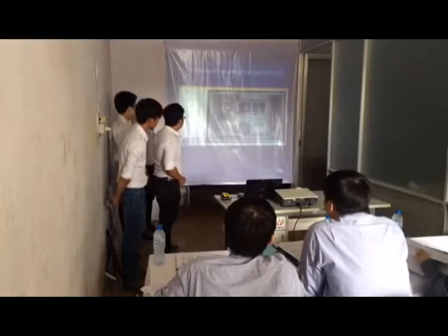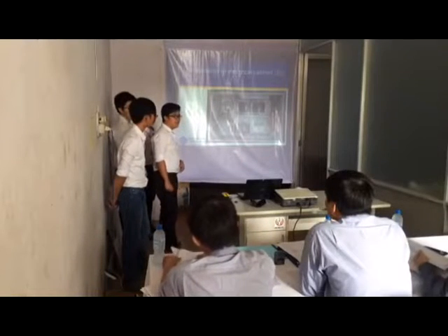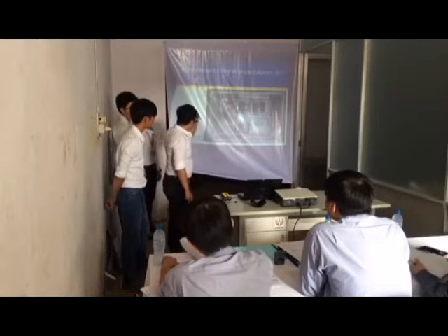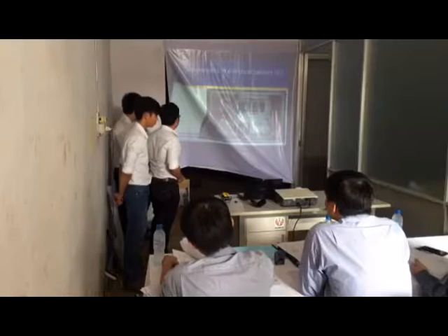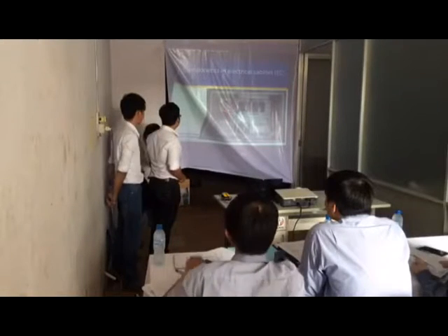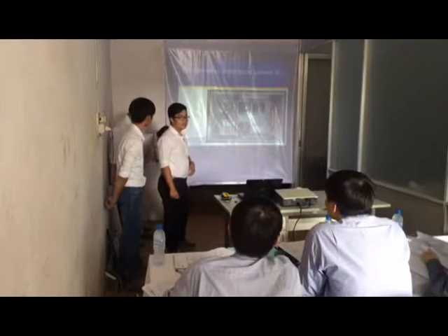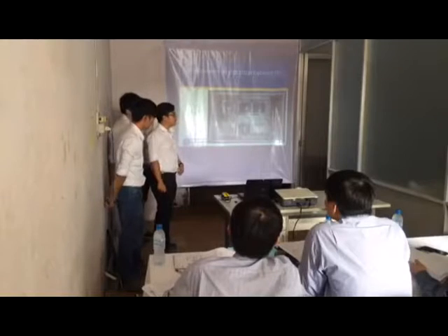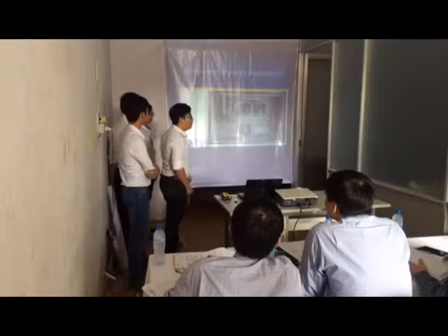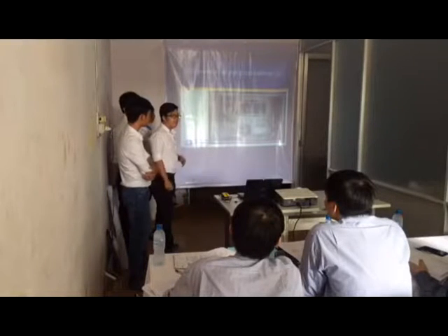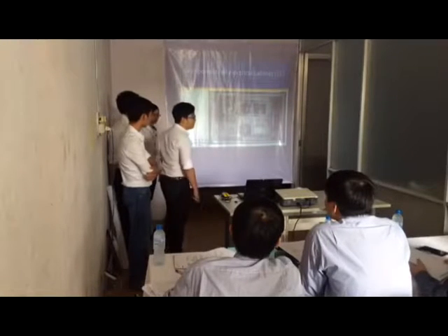Due to the X axis being heavier, it uses a bigger motor along with a larger power supply source, so we use a transformer along with a rectifying circuit to transform 220 volt alternating current to 75 volt direct current. We use a fan here to keep a stable working environment and improve the efficiency of the machine. That's all for me.